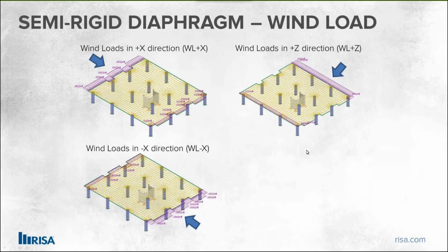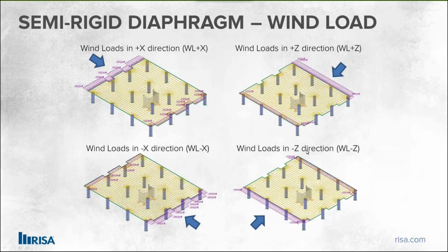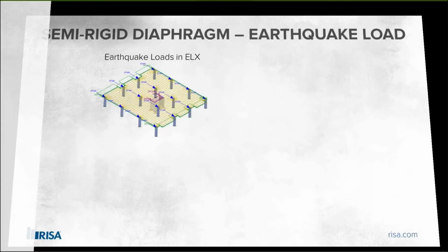Now the diaphragm load is going to be distributed through those plates to those elements. So based on the stiffness of the diaphragm, that's how it gets distributed into the structure. So we'll look at how the contours work inside of that model. We'll understand a little bit better about how we're actually distributing those loads. That's how wind is handled. Seismic is handled a slightly different way.